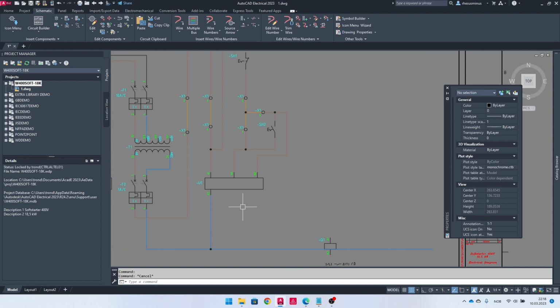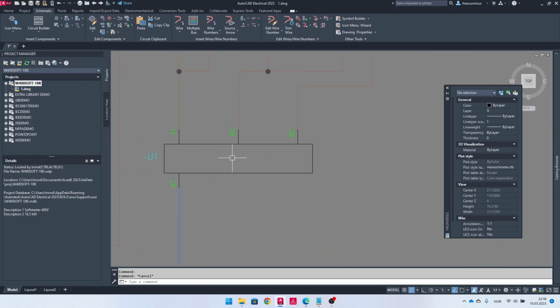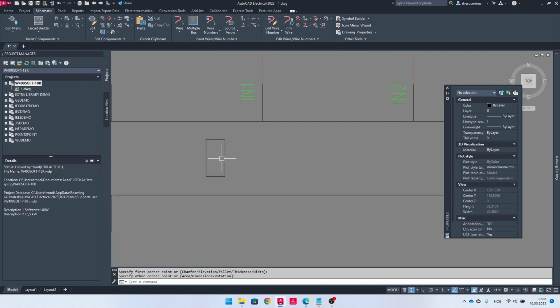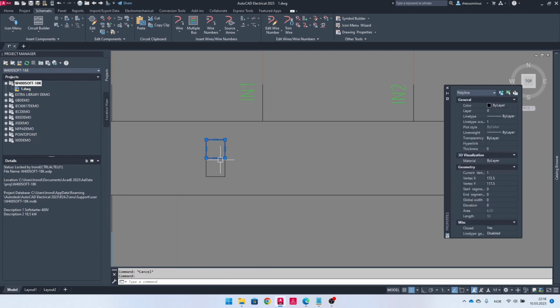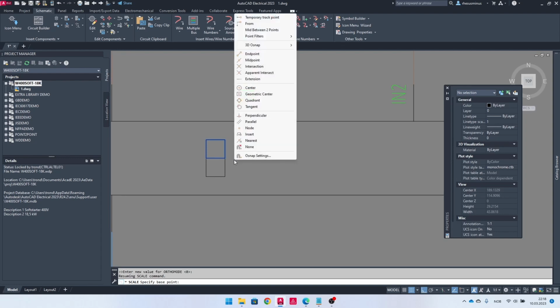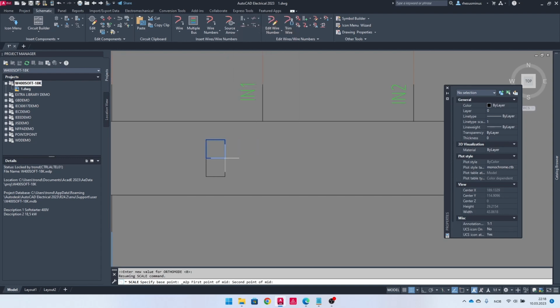Yeps, looks good. Yeah, see now from the schematics there are some dip switches that we can set here. As these are configurable, I think it's better to just have them as graphics inside my symbol. So I'll just do a rectangle, draw it like this, rectangle just like this that I will just scale, and the base point should be mid between this point and this point, and it should be 0.8, something like that.